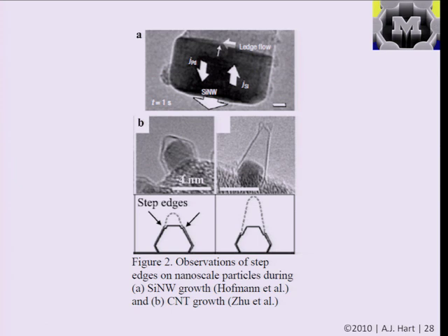And in the case of carbon nanotubes, what's being seen in most recent studies at the atomic level of the process is that atomic steps between the catalyst nanoparticle and the structure are important in essentially attaching the carbon to the particle. So here is a picture taken in the TEM of single-wall nanotubes that are the initial stages of the process, and here you see a picture of this initial cap kind of lifting off, and then the cap getting longer and starting to produce the structure.